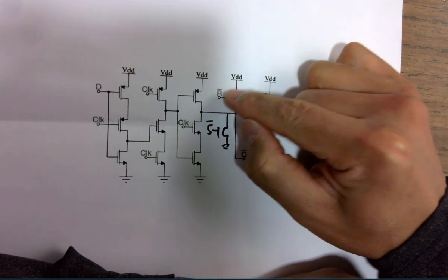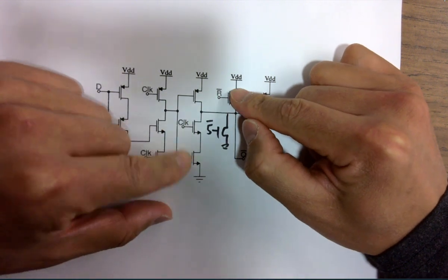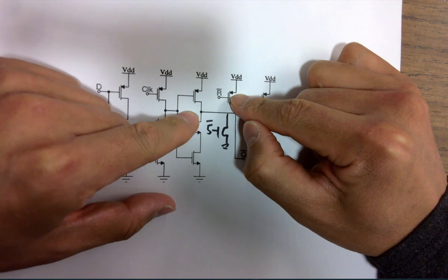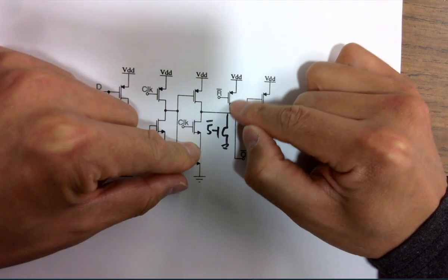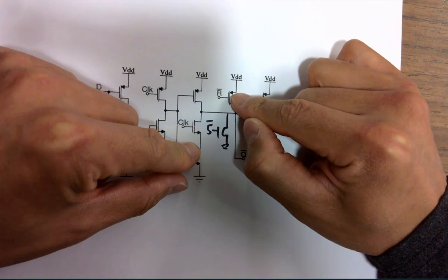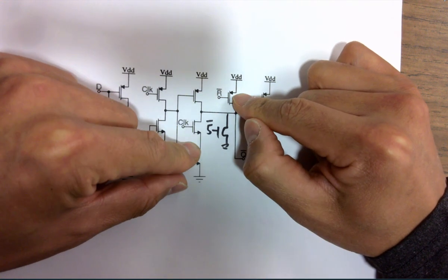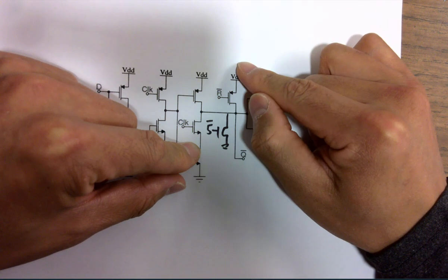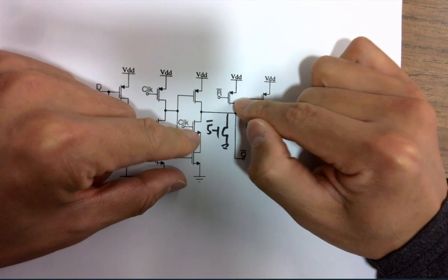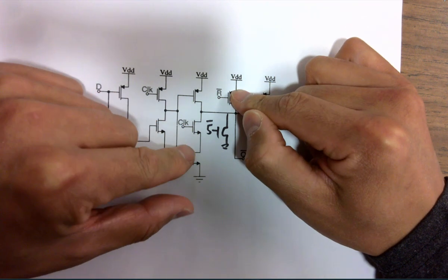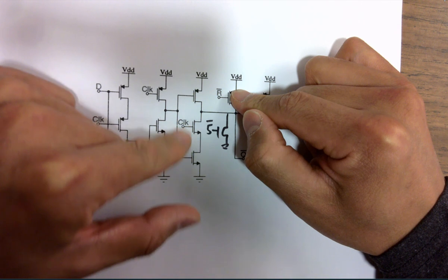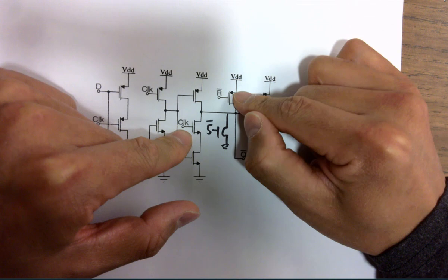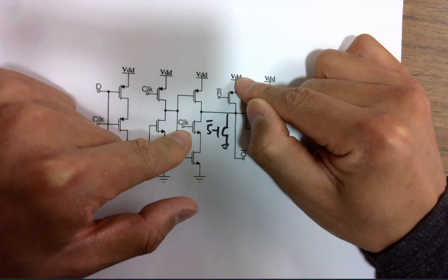Sorry, I'm resetting. So if you're resetting it, you want to make it independent of all the cycles over here, right? So if these are on, it's going to pull this down, but you want to pull this up, so just make this super strong. Make a super big and fat PMOS on the top, so you can guarantee that this will be pulled up. The thing is, this is only competing with these NMOSes, and because these are all just digital transistors, and these are not super big, I can guarantee you, if you make this huge, definitely this will be a very strong pull up.